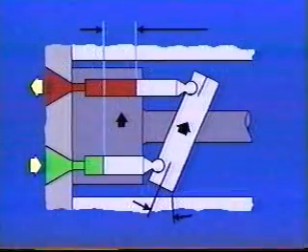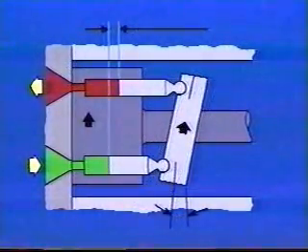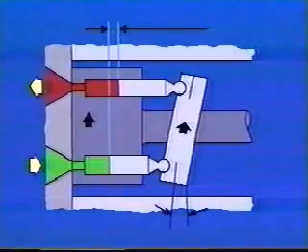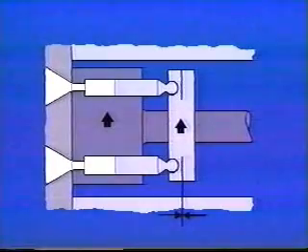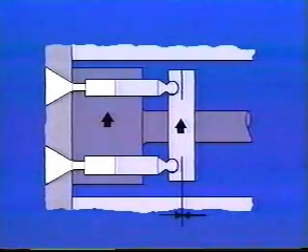The piston stroke is reduced as the swash plate is moved towards center. At the center position, the swash plate is at right angles to the drive shaft, and there is no movement of the pistons in or out and no flow into or out of the pump. Crossing the center with a swash plate would again start the pistons moving, but in the opposite direction, and flow from the pump would be reversed.